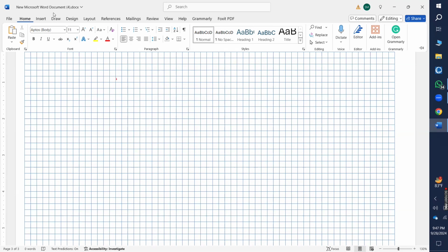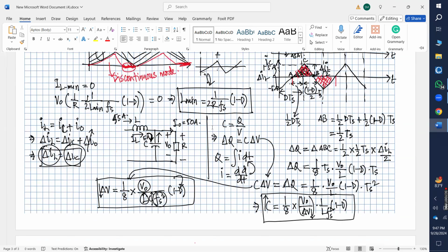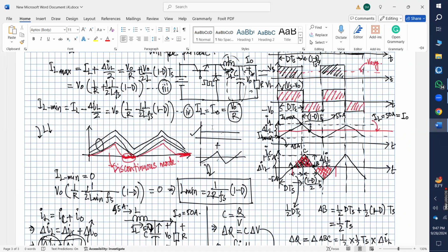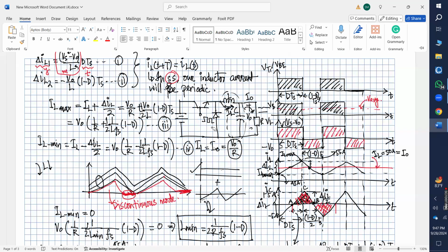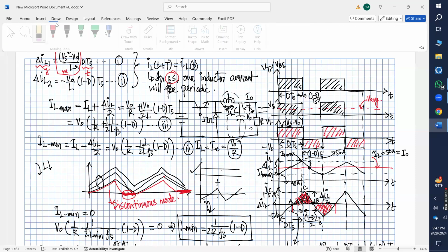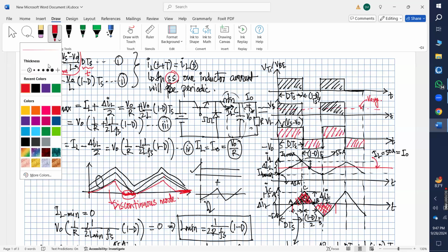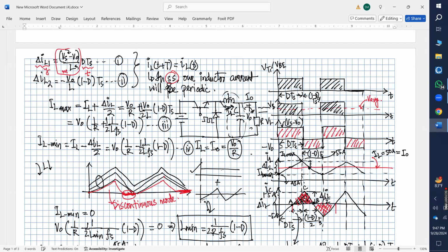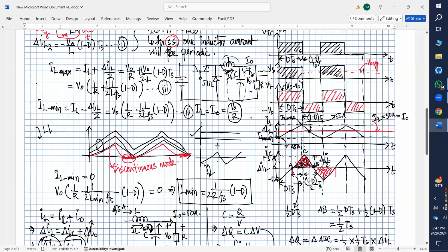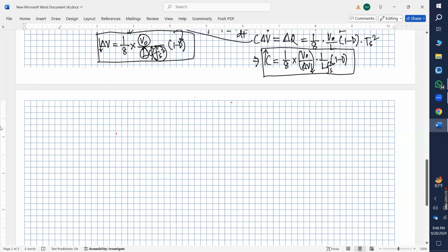Okay, so I will not start something new today, but I will just wrap up this buck converter for you. So suppose now this is the maximum inductor current, right? Yes, sir. So the maximum inductor current is happening whenever this switch T1 is on, right? Yes, sir. So what should be the current rating of the transistor T1?